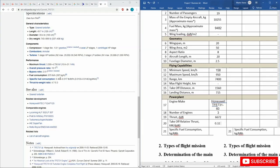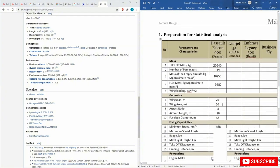So you can actually see the specific fuel consumption is here. I just transferred it to this dimension here. Actually, let me remove this bracket. Sorry, I meant the relative thrust. And the specific fuel consumption is actually here, so we have data for it, and it's 397 kilograms per hour. So it's 397, and that's it. This is the information that you needed for one of the aircraft. And now, a little bit more quickly, I will fill in the information for the rest of the aircraft, because you already learned how to find your information.